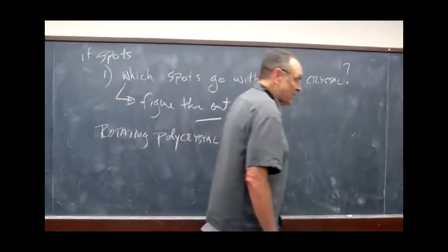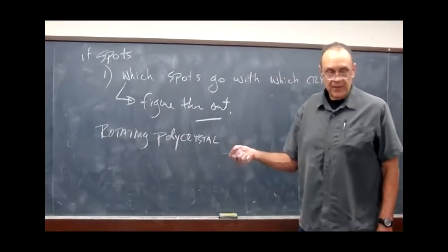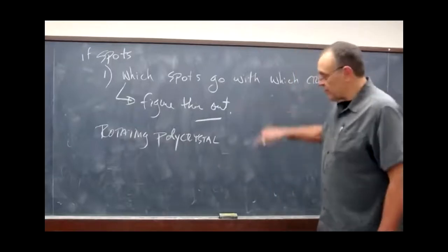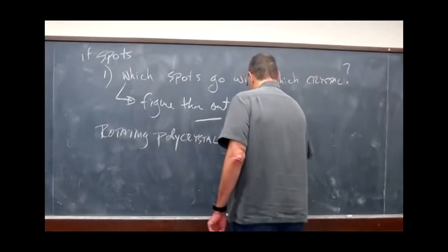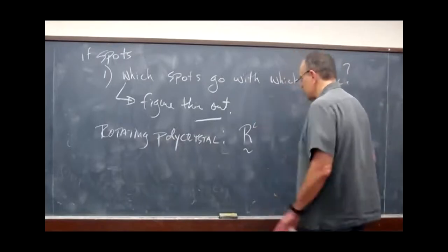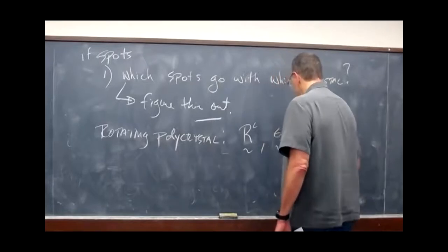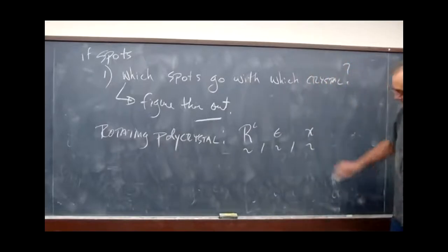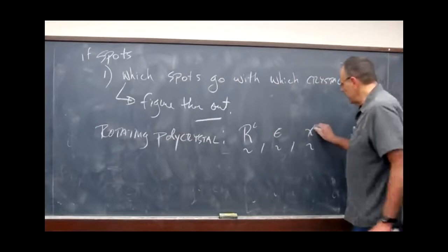Now, Darren, I think it was last week, actually did talk about what happens if your crystal is not on the rotation axis, and you define this other vector. Well, that's what you sort of do. So from the rotating polycrystal, you will get the orientation of each crystal. You get it for each crystal. You're going to get the strain tensor, and you're going to get the position of the centroid, which is pretty cool.